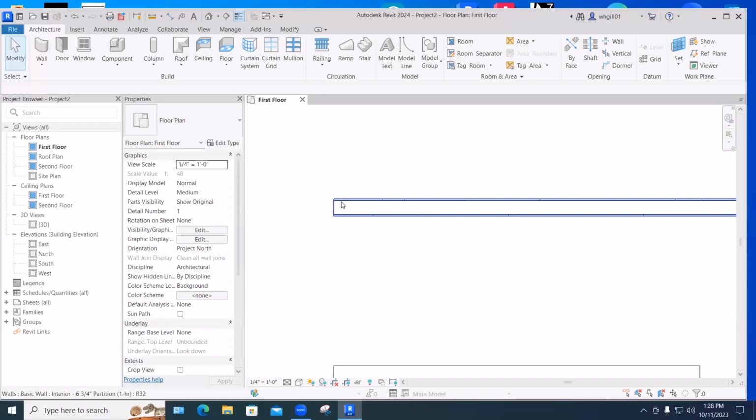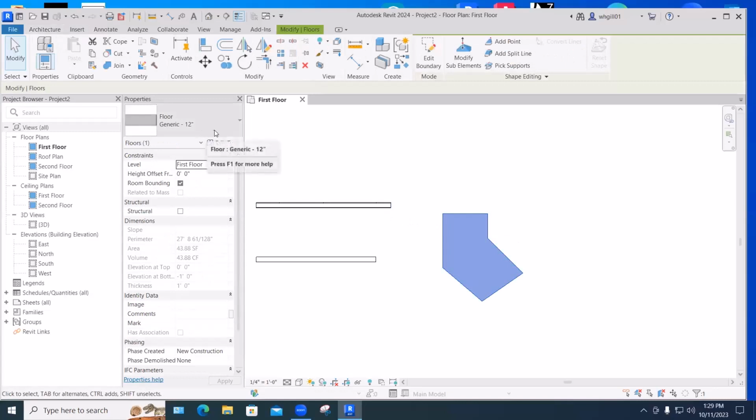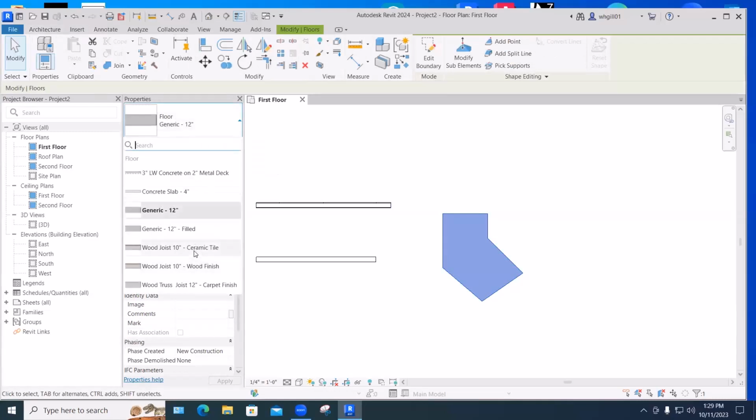So you might end up, if you're measuring your apartment, you see, okay, my wall is now 6.5 inches here, the wall behind the kitchen sink or something or other. You don't really know what's inside there. So we draw it at 6.5 inches, whatever that happens to be, just generically. And then once you find out what that is, you can change it. Walls between apartments often have 2 layers of chipboard on both sides to get a fire rating, but you don't know that until you've cut a hole in the wall and taken a look, or you remove an outlet cover to see what things actually are. So don't commit to information that you don't know about. We can switch out floors just the same way. If we want to change this to something else, we can change it to a different kind of floor.